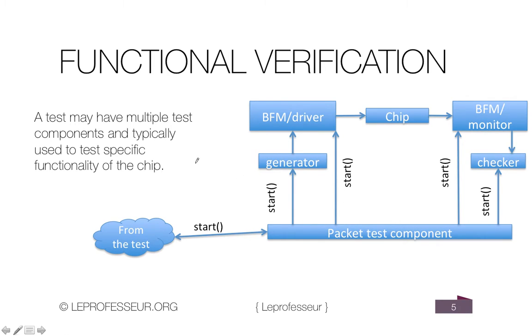So you may design a test which is like breaking that security, and want to test whether I was able to break it or not, how good it is. And we have typically, in a randomized approach, the packet approach. So we send different packets. Packet means you club together the whole stimulus stream into chunks of packets, and then you are driving those packets to the chip or device under test.